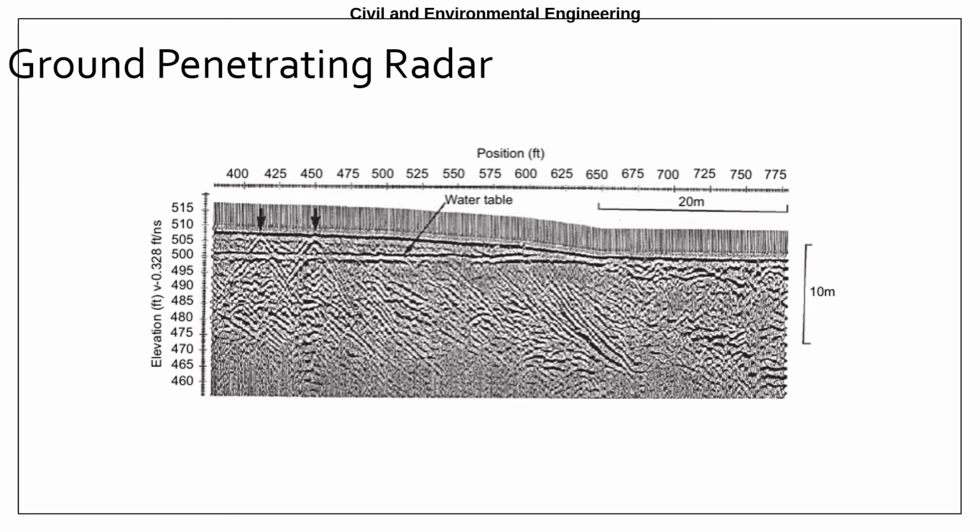A wet soil and a dry soil will have highly contrasting electrical properties or electrical readings, and when you're using GPR and encounter a sudden change in electrical properties, you get a strong reflection, or a strong outline here. So that's how you can more or less map out a water table using GPR.